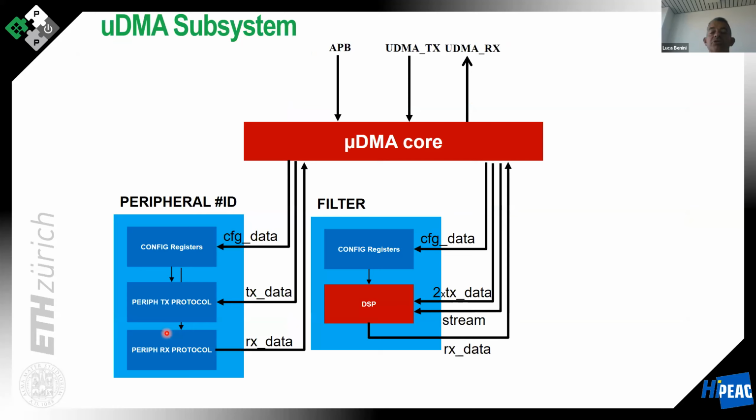So we decided to actually design an autonomous memory IO system. This autonomous memory IO system is called the microDMA, and fundamentally has the goal of managing the peripherals autonomously and implementing memory transfers from the peripherals directly to the on-chip memory with minimal intervention from the input-output core that we have into the SoC domain that is not a cluster.